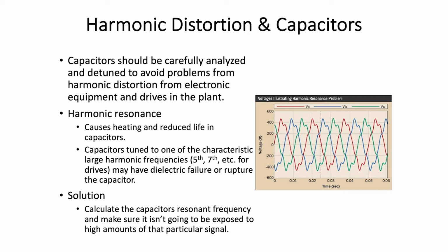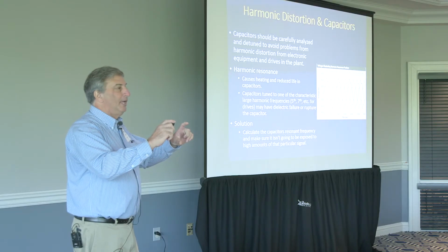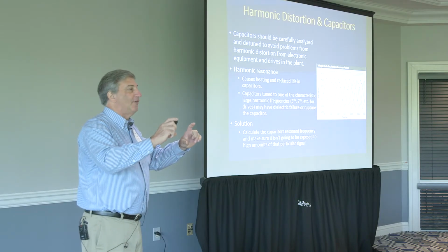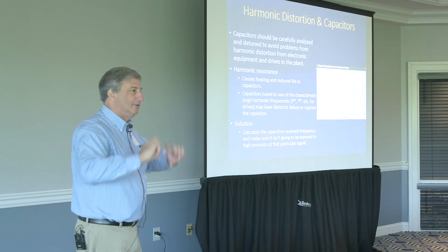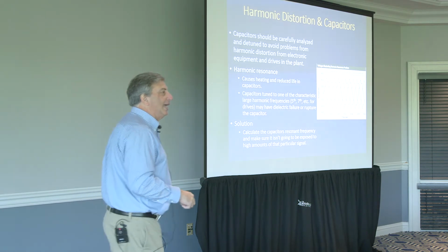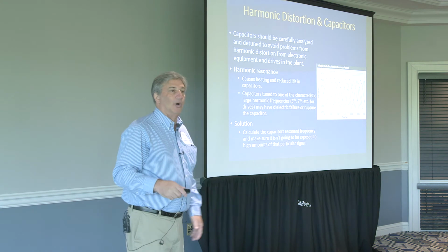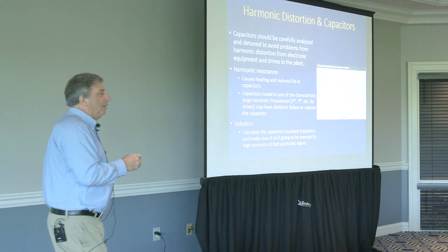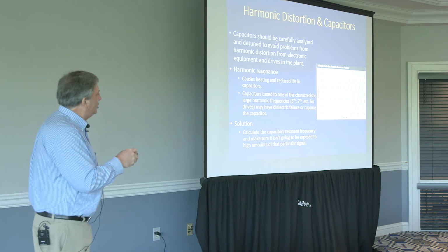That resonance creates heating and reduced life in the capacitors. I've seen it produce enough vibration that the capacitors vibrate and tear the mount up, and pretty soon the capacitors fall off the mounting brackets or bolts and are laying in the bottom of the panel, or worse. So this is another fairly common issue.